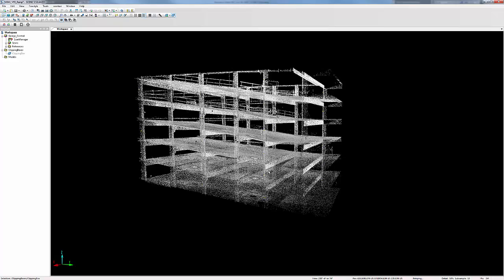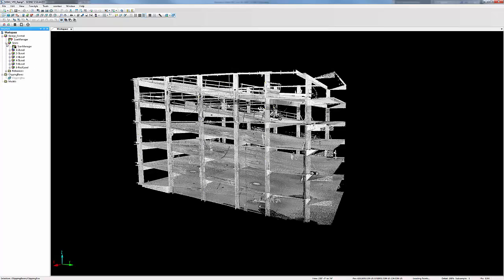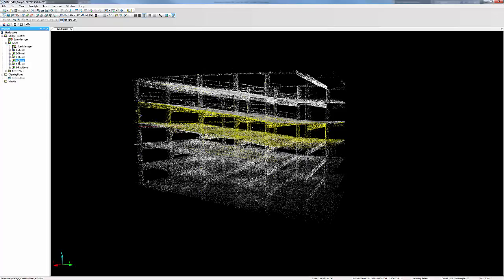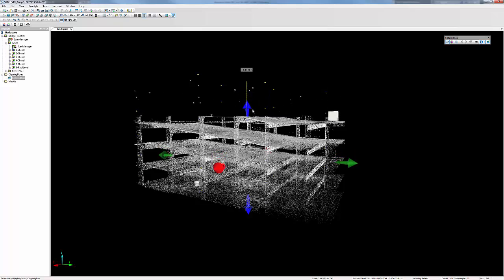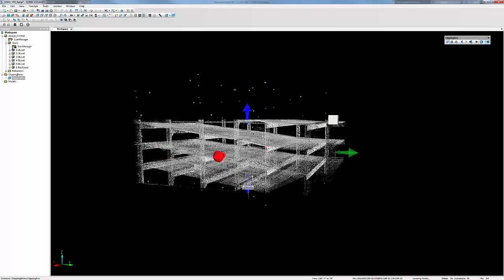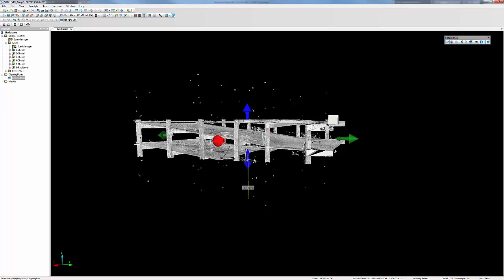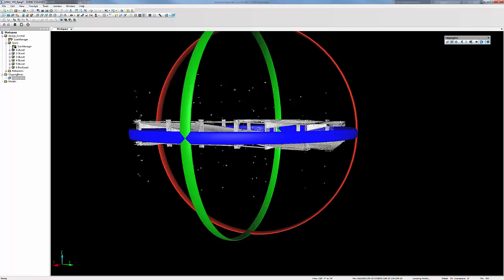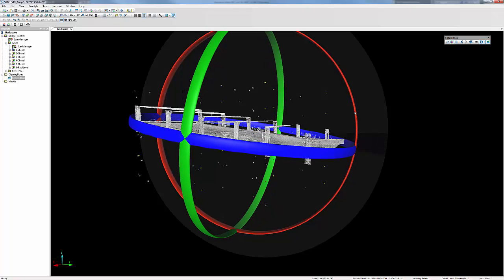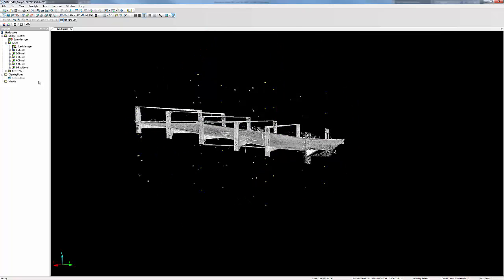Going back into 3D view, we're going to run a quick quality control and make sure that everything came into place correctly. Our original point cloud that we exported and imported into AutoCAD was our level 4. So we're going to isolate that using our clipping box. It's pointless because we're just going to export the cluster.